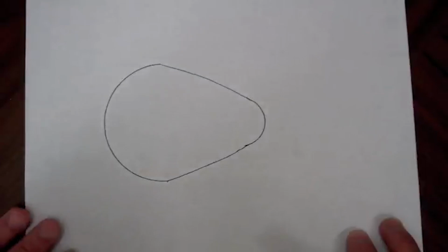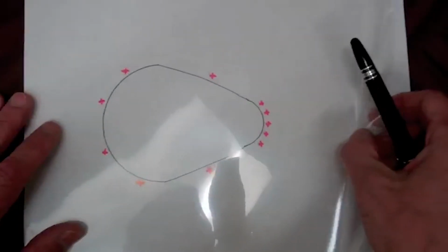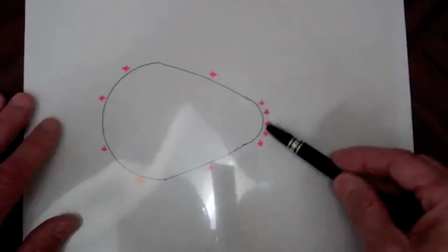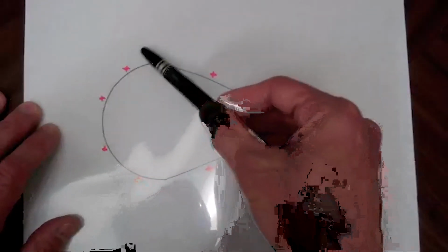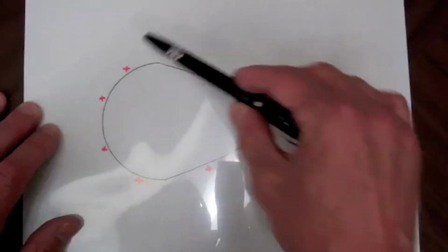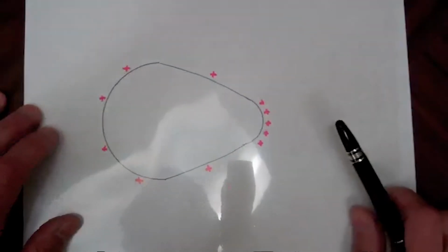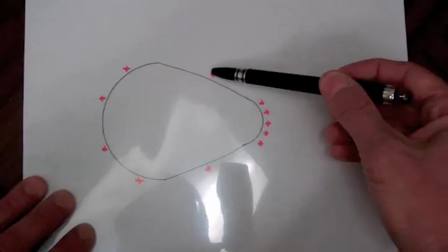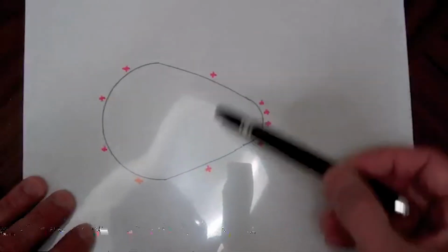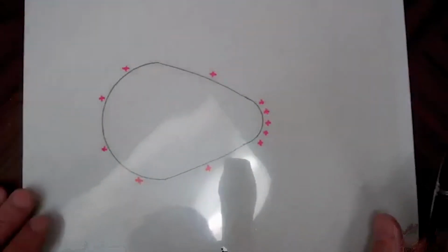And from the experiments we just did, we know that the charge density would look maybe something like this, with the greatest charge density here where we have the greatest curvature, then a little bit less charge density here where we have the slower curvature, and finally the least amount of charge density on these two ends here. And we know that the electric flux density lines will come out normal to the surface because this object is an equipotential object.